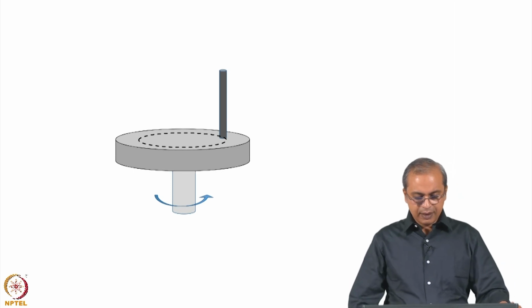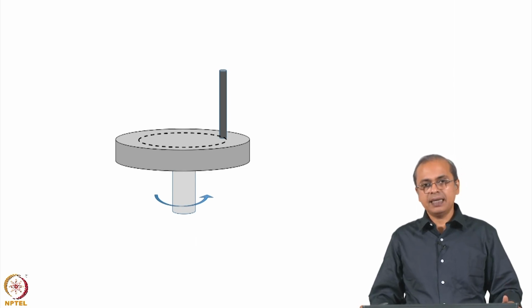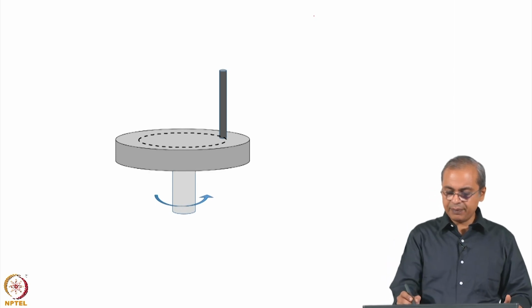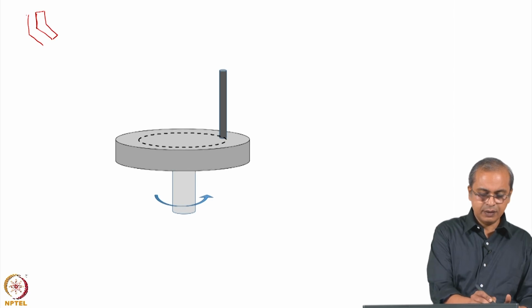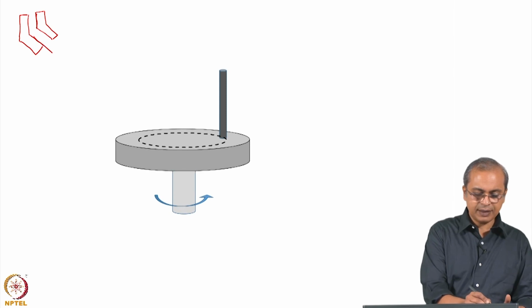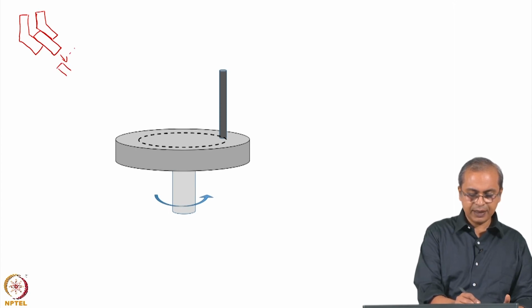Okay, so if you look at a severely plastically deformed sample, as I said, you are having multiple passes through dies which are shaped like that. And so, the sample that comes out still has the cross section that it originally had, but it has already undergone significant severe plastic deformation, and then you can put it through one more pass like that.